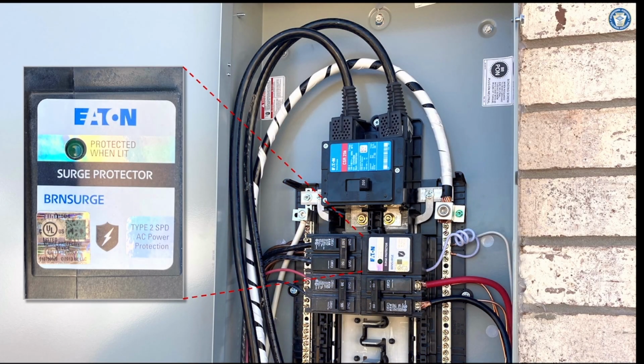This is a good picture. You've got a surge protective device here. Now, remember, in the 2023 NEC, this is required to be a 10 kA I_n, okay? You've got to be mindful of that. Make sure that whatever surge protective device you're using, you're picking the right one. You're noticing the barriers. There's your barriers, and then here is your bonding.